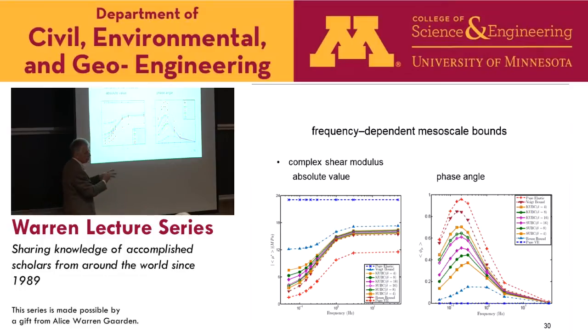There's no crossing of bounds, nothing, everything goes like that. And once the numerical work is done on a PC, then one basically has a description of a random viscoelastic material as a function of scale, because this is the mesoscale dependence. And, so, of course, one can back out here the effective response with good precision.